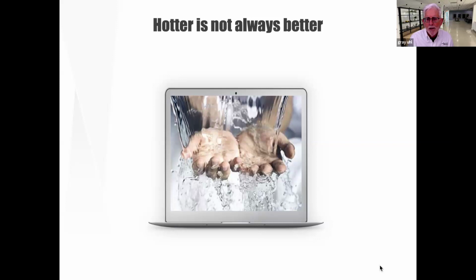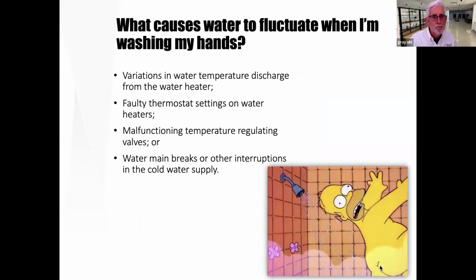This is true at hot water heaters themselves, which typically can get set at 140 degrees. And the reason that a public hot water heater would be set so high is that they're trying to kill off Legionella bacteria. So that's a different goal than the germicidal effect of hand washing. Those are two different things. So we need to make sure that we disconnect those things: hot water temperature versus the water that's being delivered physically at the source.